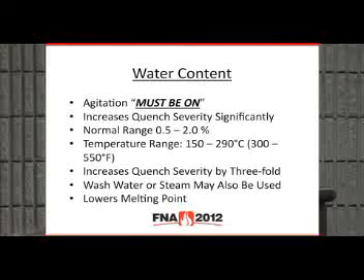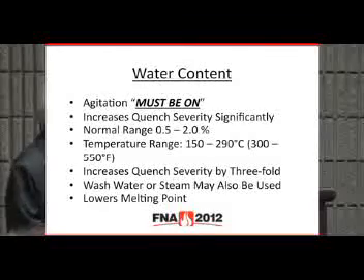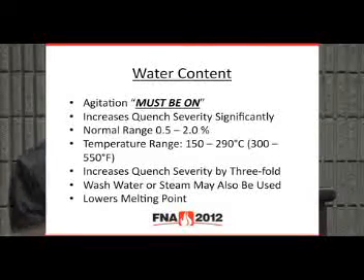And with the combination of agitation and water content, the quenching severity can increase by 3-fold compared to salt that does not have water and is not agitated. Another fringe benefit of adding water is that it lowers the freezing point or melting point of the salt, so it gives you a little more expansion of operational limit.